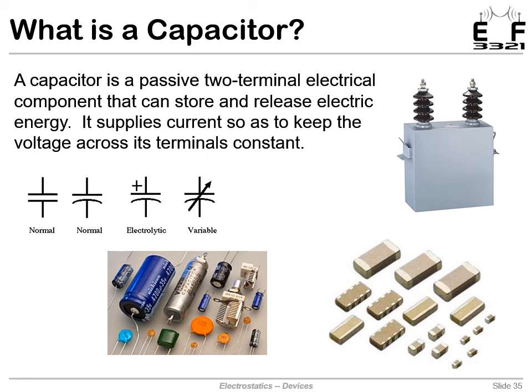And in fact, in the older days, before cameras were using LEDs, they were using flash lamps. Internally in the camera, they would charge a bank of capacitors and discharge them so it could supply this huge burst of current to the lamp. The lamp didn't take a high voltage, but it needed high current. And in fact, you could even hear your camera charging, and you could only take pictures so quickly because it would have to charge the bank of capacitors back up. That's not really a problem today.